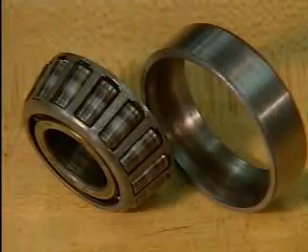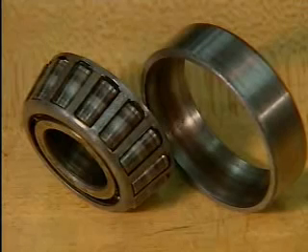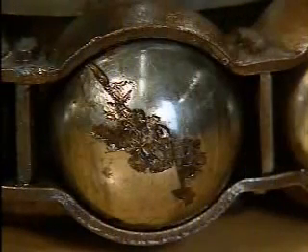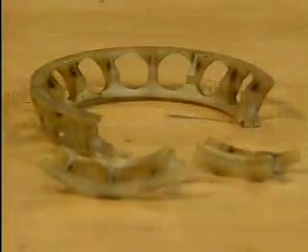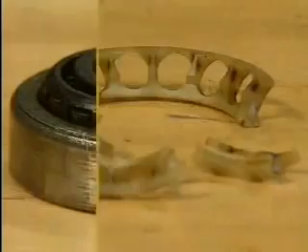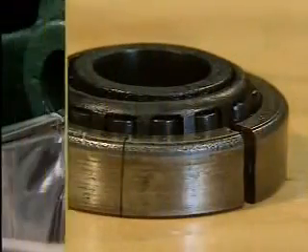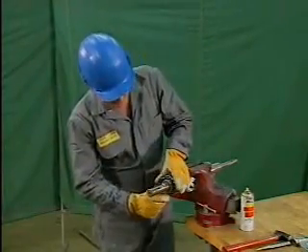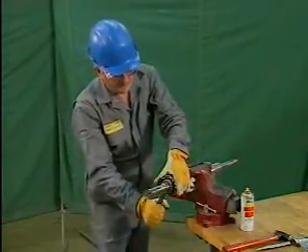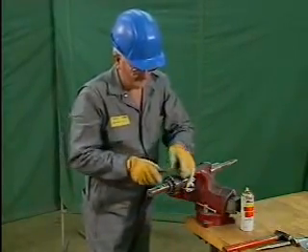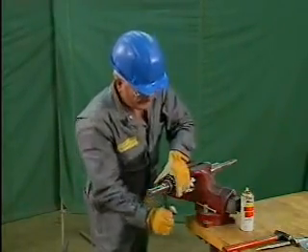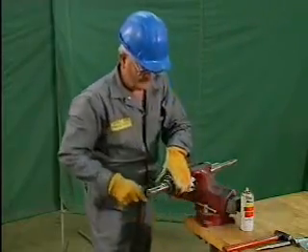This evidence may include burn marks, which are blue or brown marks on the rolling elements or the rings, spalled areas, which are places where the surface of the metal has flaked away, a bent or broken retainer, cracks in the rings, and discolored lubricant. If the bearing failure is unusually severe, all of these signs could be present, but not all of the signs are necessarily present with each type of failure. Let's look at some common types of rolling contact bearing failures.